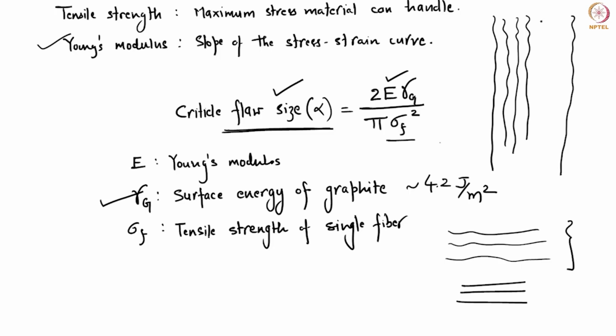Now you increase the temperature. What will happen? Some of them may actually align and form graphite crystallite. However, now when this space decreases, because the spacing between the sheets is decreasing, there may be some voids created because we are not supplying any material from outside while our structure is shrinking, and it is shrinking in random ways. It's not necessarily one big graphite crystal that is forming. So you may end up getting certain voids or certain flaws.